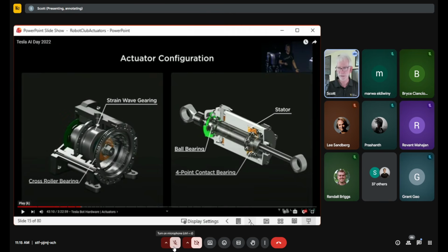So motors are going to need bearings because they're going to be receiving a lot of forces. And so sometimes the bearings aren't just to keep the axle straight and make sure it spins really well, but you might have to have these cross roller bearings in there to be able to take loads that are coming from the radial direction as opposed to axial. So that has to be a consideration that we're going to talk about as we go forward here.